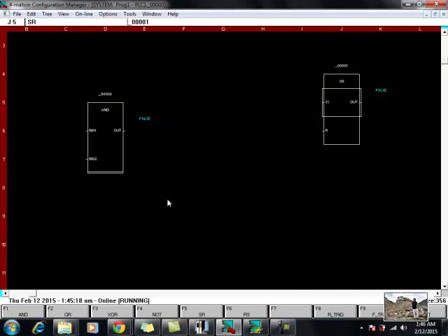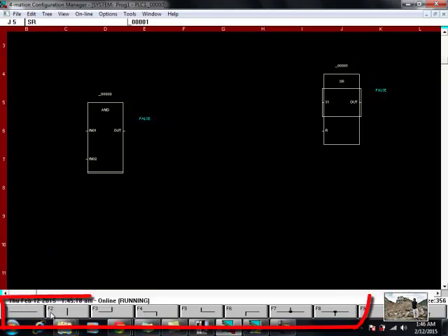Now let's start our connection process. To do that, at the bottom in the menu, you click the next button and look for the function wire. If you don't see the function wire, you press the escape button on your keypad, so it will bring you one level up. Now you see there's wire in F9 at the bottom right side, and you click on the wire function. After you click on the wire function, you will see different options, different ways of wiring connections.